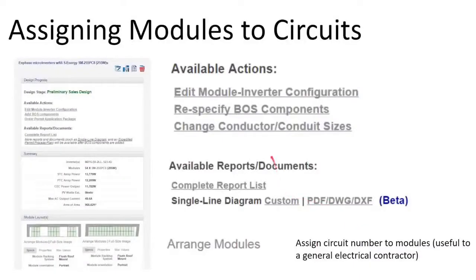Solar Design Tool has a plethora of final design detail documentation, more than really any other software. It provides the most detailed out of the box one line diagram, which is pretty impressive given that it's kind of on the low end of price. With the caveat that its tools are really geared towards small residential projects, 4 circuits or less in general. Sometimes I'll model larger projects and then stitch them together in CAD afterwards.